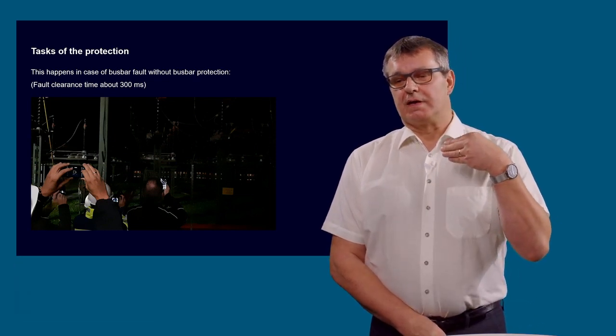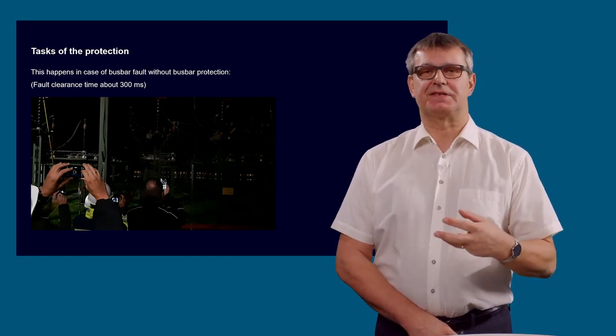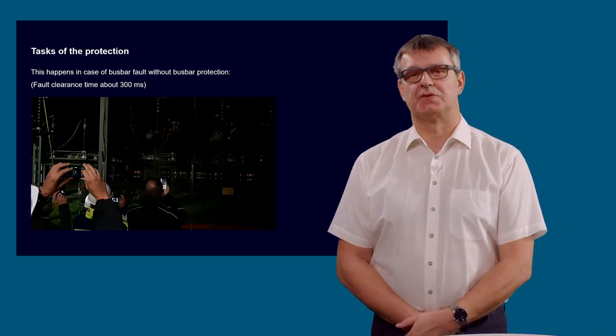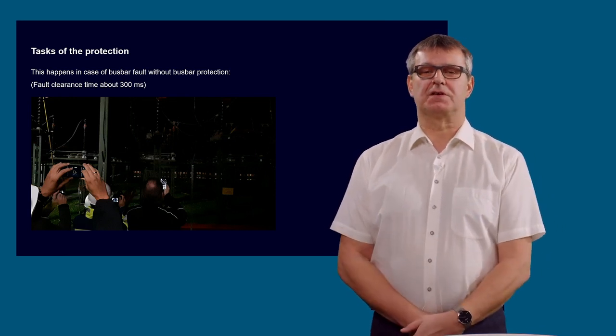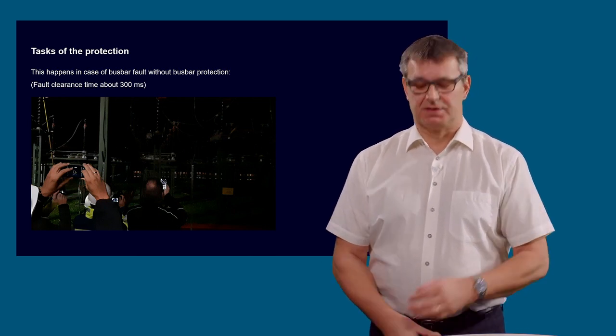how necessary a dedicated busbar protection really is. In high voltage, to have only a backup protection of 300 milliseconds of the distance protection for the busbar is really not state of the art.